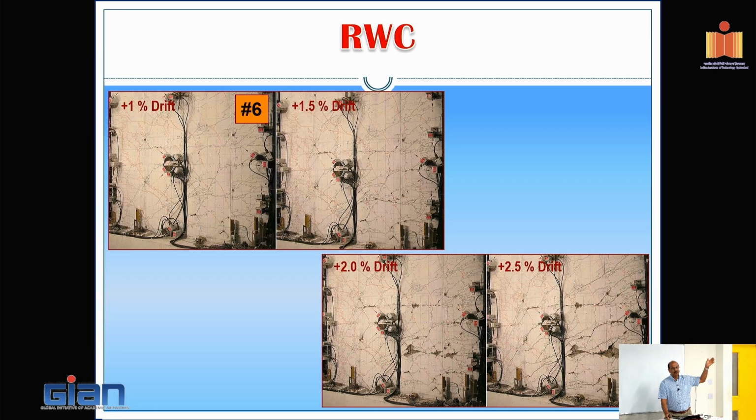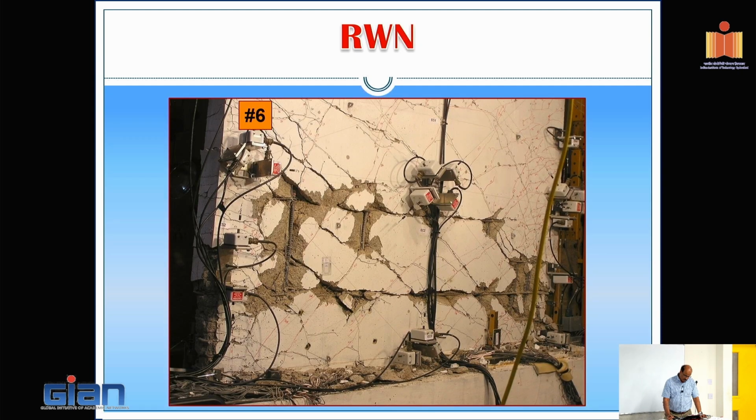The example we looked at, the emulation is going to look like this. So look at the extent of damage here. Now take a look at the wall without any splices. That's how it looks. So this plastification is a lot more distributed. You're still going to have areas of concentration, so that's what you're seeing here. You can see the flexure crack, you can see the shear crack. So this is what we were trying to sketch in the very first place, right?